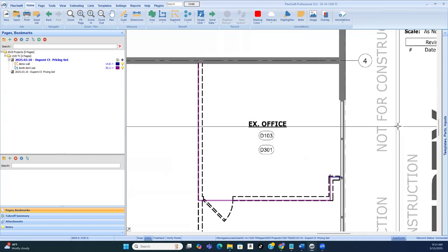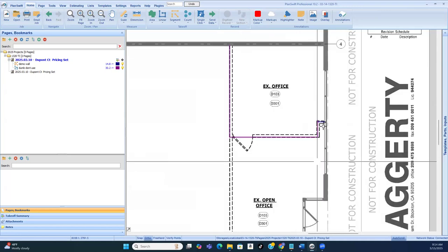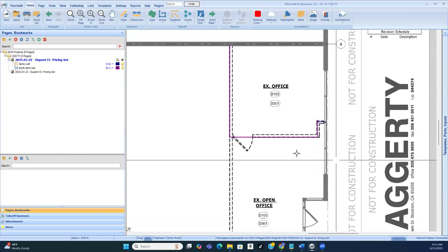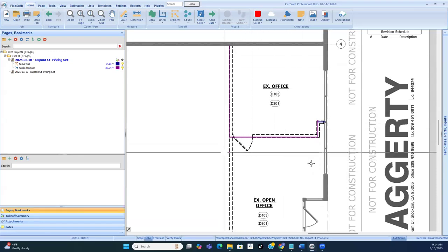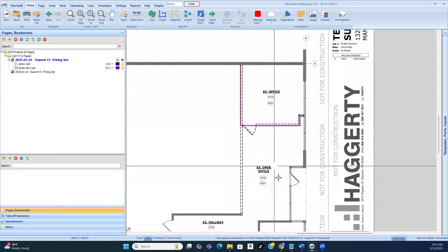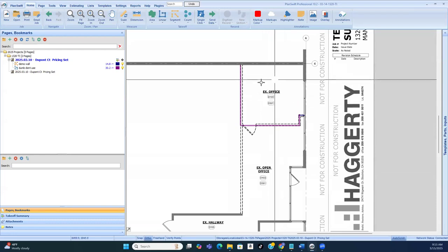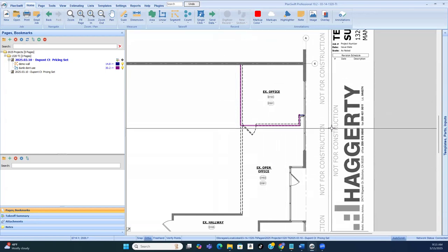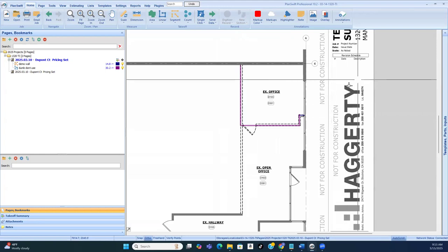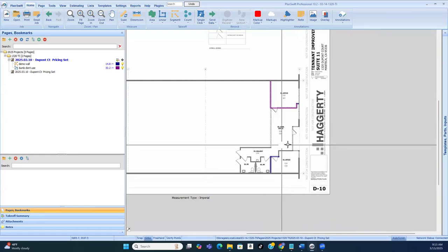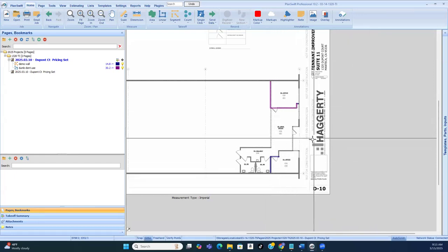Well then I gotta go to my spidey senses and say, okay, I know an electrician says there's an outlet every 10 feet or something. Okay, well, I'm gonna assume every 10 feet there's an outlet and the light switch, and these are commercial offices, so those two by four troffer lights or whatever. I'd estimate there's two every two. There's a standard for that, and that's what I would give them on my estimate based on da da da da, to be adjusted after site visit.